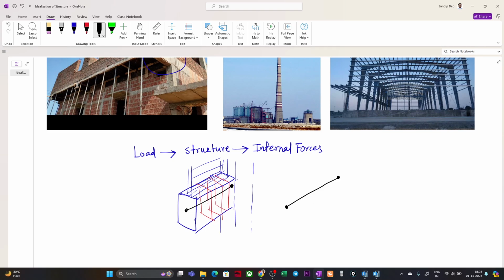So this is basically a concrete block having 3 dimensions, having some properties, some moment of inertia, some stiffness, but we consider it as a line. It is also having similar properties, that we are assuming, or idealizing. Now we have this brick wall. We cannot model this brick wall while analyzing it. So what we do is calculate the load of this brick wall, and this brick wall is there throughout the length of the beam.